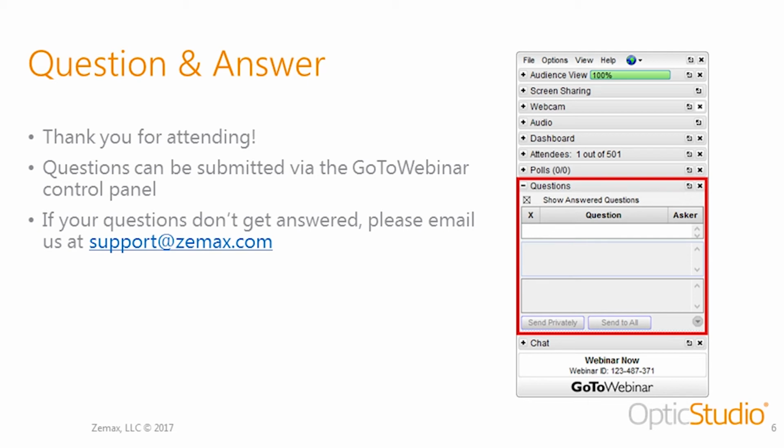Okay, so it looks like the first question is, when you use the slider to adjust the parameters, is focus occurring also? So I'm guessing that this is referring to either the quick focus adjustment or paraxial focus adjustment. And the answer is no. The slider and the visual optimizer are only changing the parameters that you see in the editors. There's no additional compensation or adjustment that's done once you manually change them or drag the sliders.